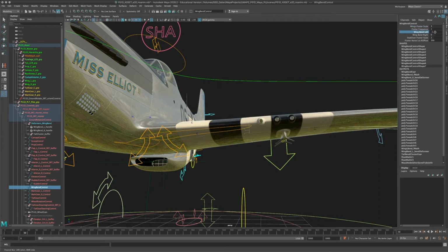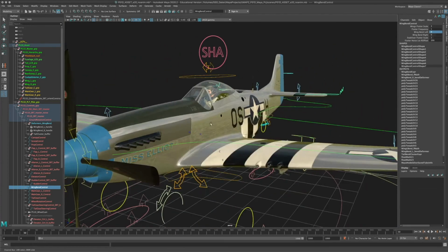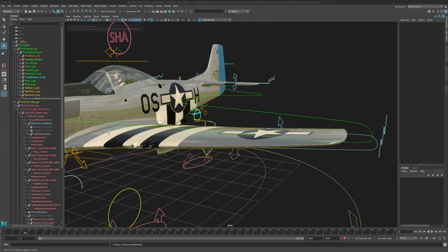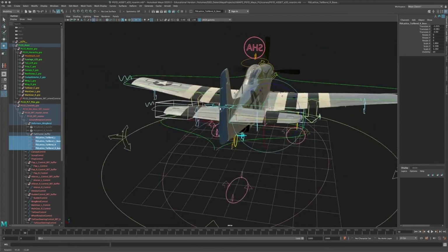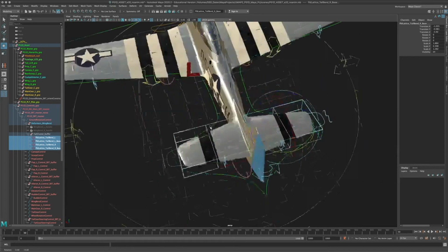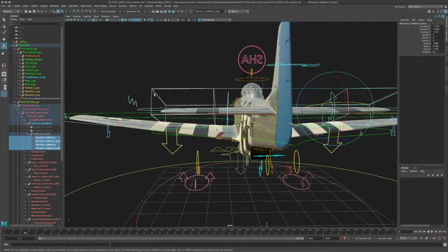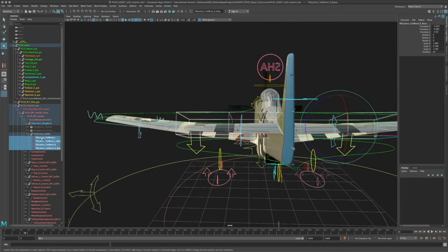So that works. The bend deformers are responsible for the main wings, and for the tail surfaces, for various reasons a bend was impractical there. I used Lattice deformers again, and I selected the points on the outer edge of the deformer, and I clustered them.